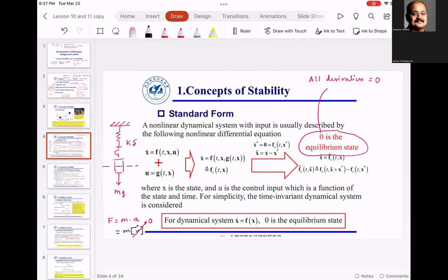So stability about a fixed point is, Mambo is flying in a level flight, just stationary. If you push it, you pull it, move it left, move it right, it goes back and stays steady. This is called stability about the equilibrium point, and that we will achieve first. So in the assignment, once you do the complementary filter, and I will tell you the loops that you need to implement, that will be used to achieve the stability about equilibrium.